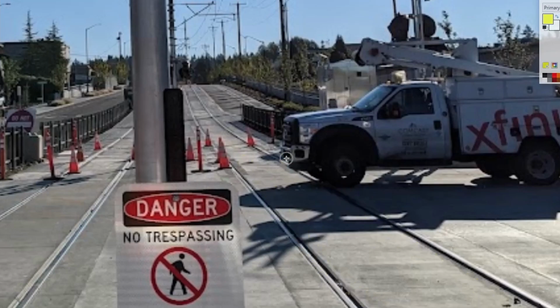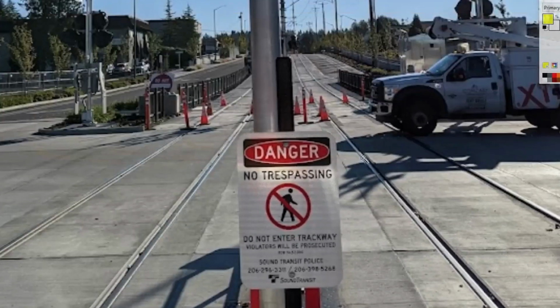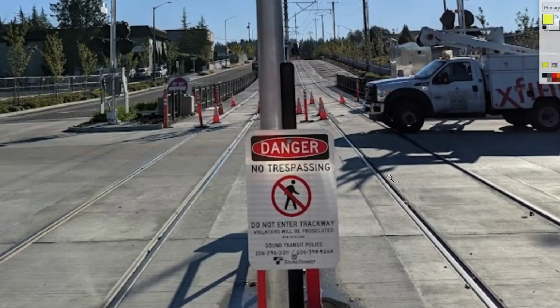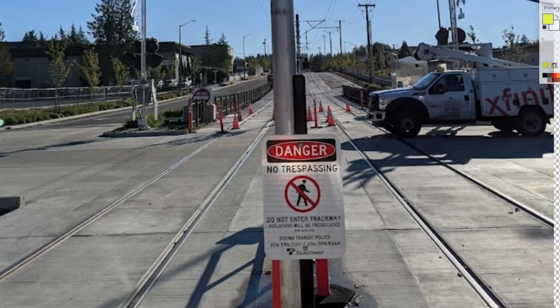It depends. Sometimes they'll use direct fixation track and pour over the top. Some places have used just the rails set into concrete and prayed, which is not the best, but it has happened. And sometimes there are ties underneath as well. But when you pour the concrete over top, you can't get at it for maintenance. But this also gives kind of a neat rail profile that's really fun to see.